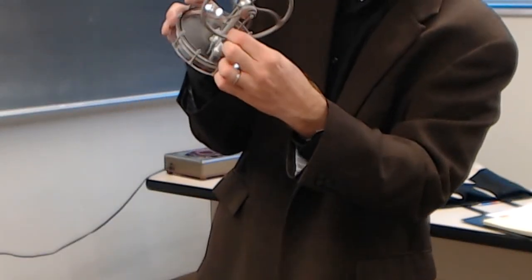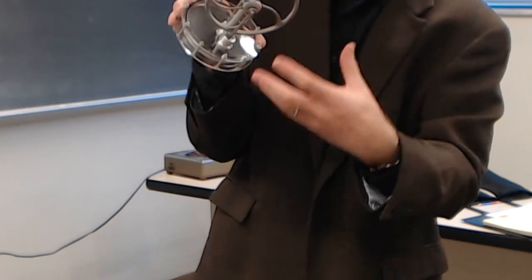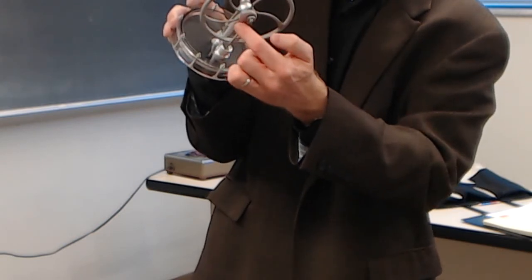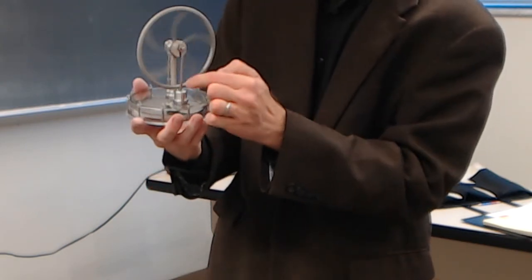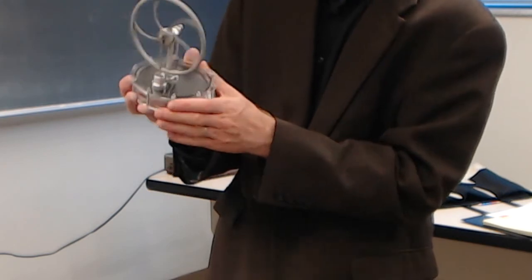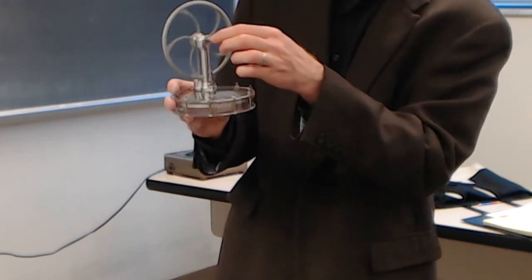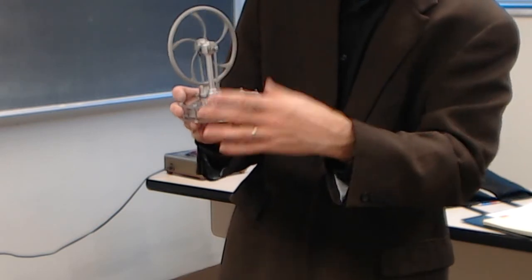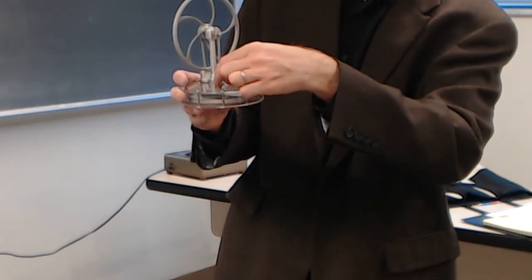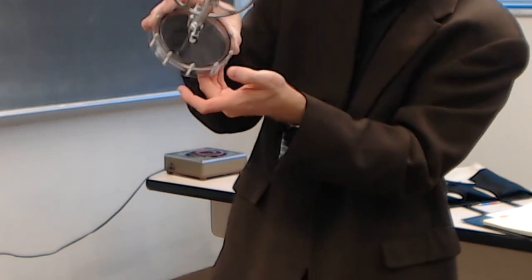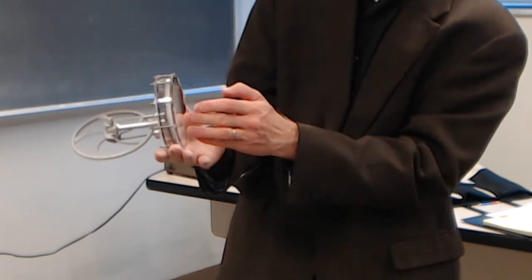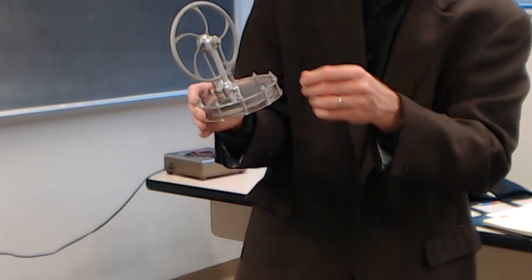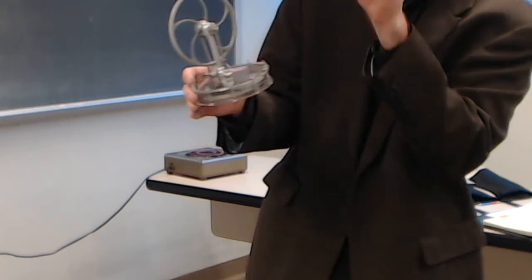Its construction has it with here the piston, all right? As the pressure increases, it pushes that piston out, which turns the crankshaft and the flywheel. In order to change the internal state here, the crankshaft then also pushes this, which is a displacer. This is not a piston inside, that black styrofoam there. That's actually a loosely fitting displacer that simply shoves the air from the hot side to the cold side. Actually, I'll have this the hot side and that the cold side.